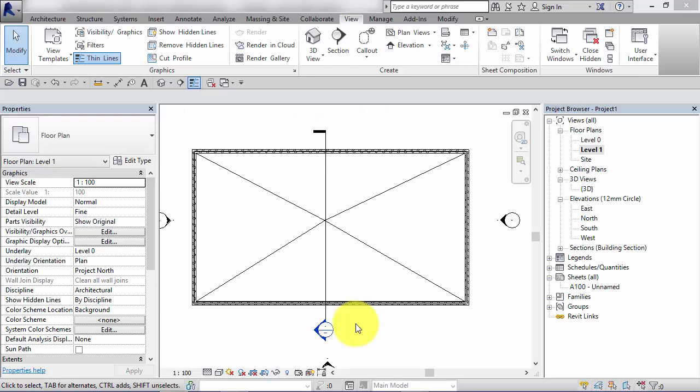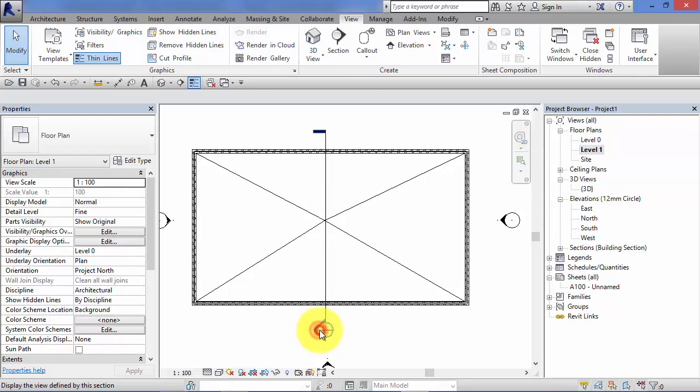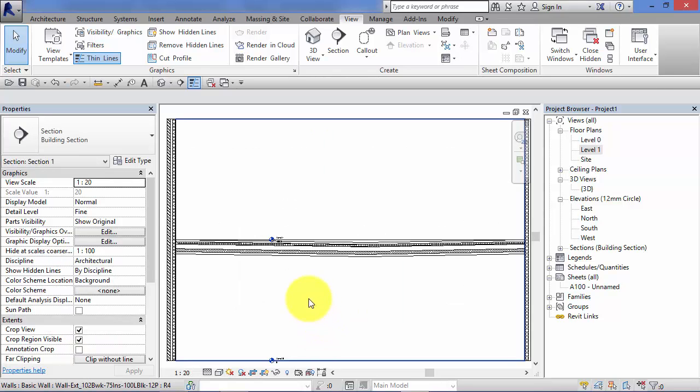Now I mentioned before about variable thickness layers. So if we go back to the previous example where we added a single point at the center of our floor, I've set that point minus 90 mil down just to make the slope a little bit steeper so it's easier to see what's happening. If I switch back to that section view, notice that the whole floor slopes down, so all the layers stay parallel to each other. So the bottom of the floor, the underside of it, is sloped as well.